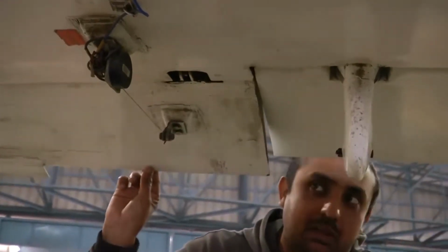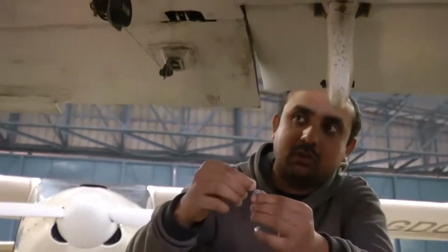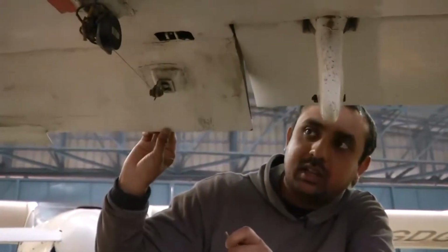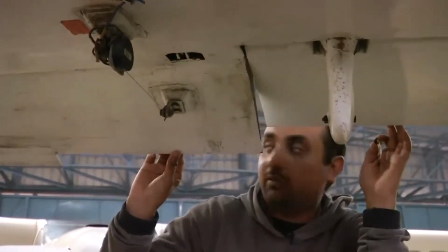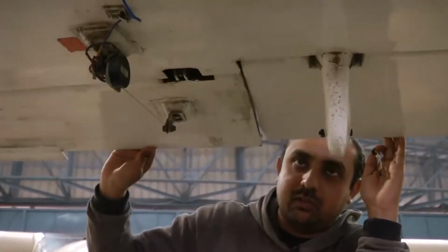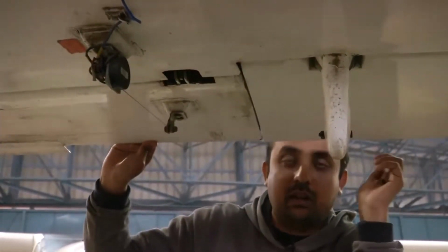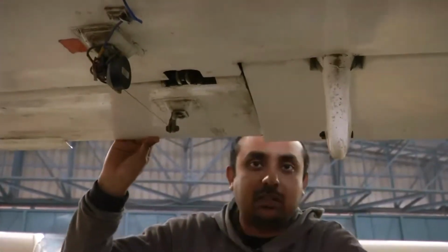It works on the same principle, but instead of this manual rotation of this contact switch, here a string is attached that is varying the resistor, and according to that the voltage varies for different deflections of this control surface. Now, we will be seeing how to perform the experiments.